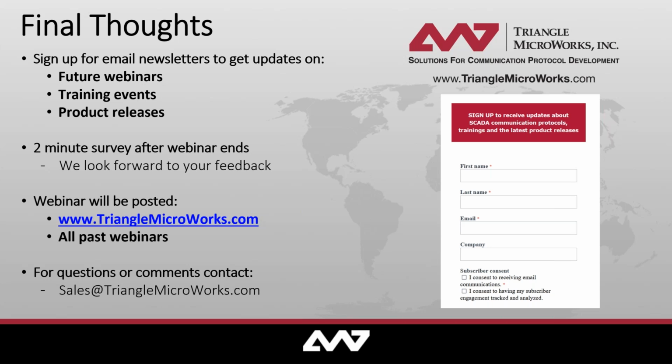Also, in Goose messages, we typically don't include a timestamp, also just not to overload the communication. If you would include all the timestamps in Goose messaging as well, so that you can subscribe to that and get your timestamp of the information, that will create much more overhead. So using reporting up to a client is definitely the more efficient way to use our communication.